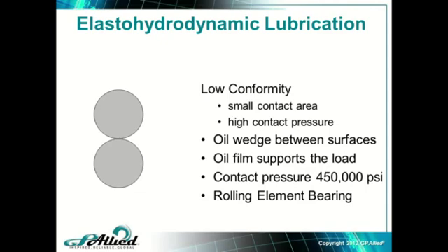As that oil wedge passes through the load zone, everywhere, if you could freeze that situation in time, and we got a graphic of this coming up, you could actually see that the face of the race, just under the roller, directly beneath the oil wedge, is compressed. And then when that oil wedge passes by that spot, that face springs back up. And as the next oil wedge comes by, basically the next roller comes by, that spot gets compressed. And when it passes, it pops back out. So this is why we say the steel has an elastic property.